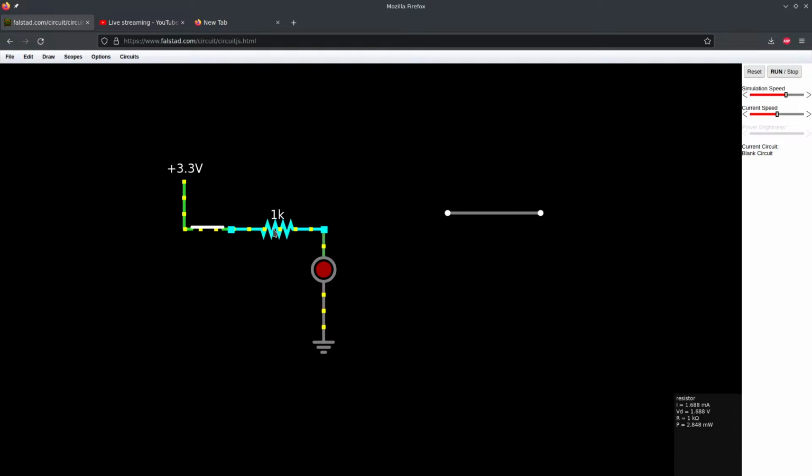The actual calculations are more complicated, but usually something around 200 to 1,000 ohms is fine for connecting from your microcontroller. It's the formula: the voltage minus the voltage drop, divided by your resistance.